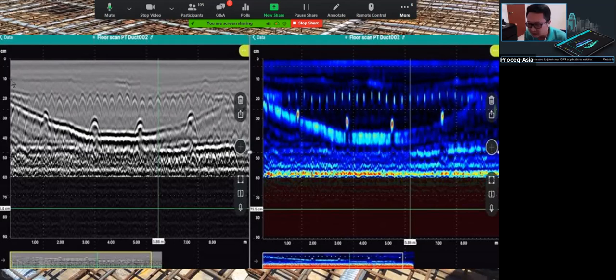But we can also see a small interface around 10 cm, right? Then on top, there's some other facade material. Over here, we can see the whole geometry of this post-tensioning along the measurement line. And importantly, we can see the second layer rebar and the total slab thickness in this measurement.